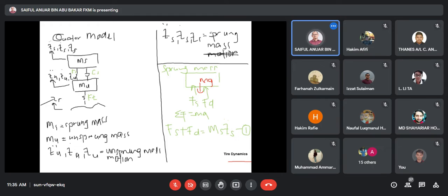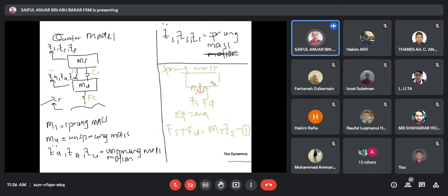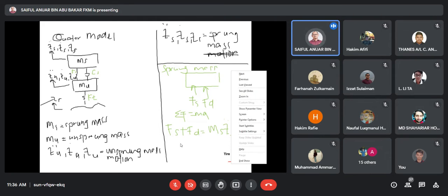We eliminate this mg term from the beginning, because otherwise our response will always be negative and we would need to offset the graph by the mg value. So rather than eliminating it at the end, we eliminate it from the beginning. That's why we won't have any mg terms in our equation. So don't say the diagram is wrong; we simply assume it's not there. This is the first general equation.